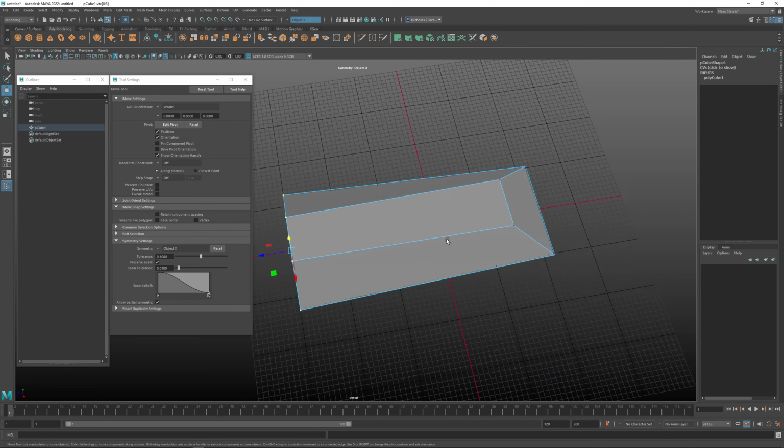So the next level up, we're going to go to 2, and it's going to take each one of these faces, divide it 4. It's going to take this face, divide it 4, and so on across the entire object, and do another smoothing algorithm on it. So you can see as we go up to this level, we're starting to get finer level of polygons on there. If we jump up to the next level, it's going to take each one of these faces and divide it into 4 and keep doing what it's been doing. But you can see it's starting to get more and more resolution across the object.